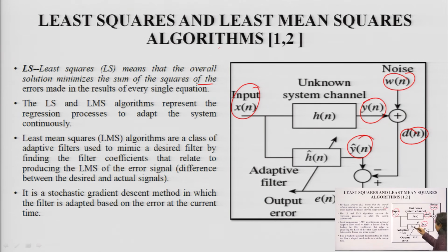Then here there is an h cap n. Now, what is h cap n? This is again an equalizer, which is the predicted value of H n, and its value is being changed, which means it is a variable adaptive filter. It is a kind of adaptive filter whose transfer function resembles this H n. Now, this is applied as an error to this adaptive filter output error.